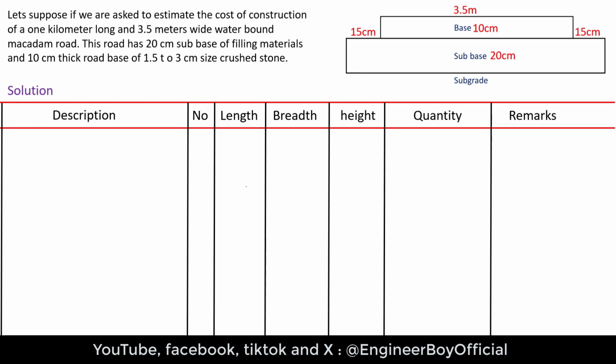The first thing, as you can see, is subgrade. It means that subgrade preparation is important. You can say the dressing of subgrade, and if there are any trees or rocks, those are removed. Even at this stage, in preparation of subgrade, gradient and camber are considered.